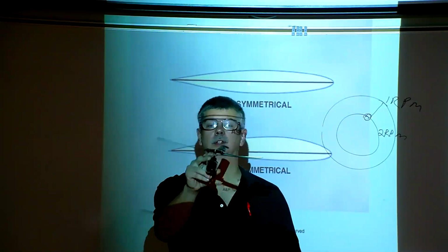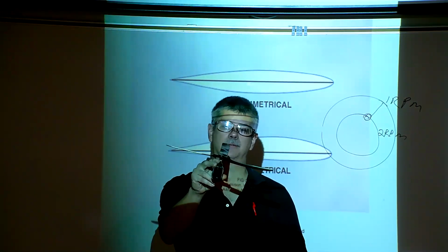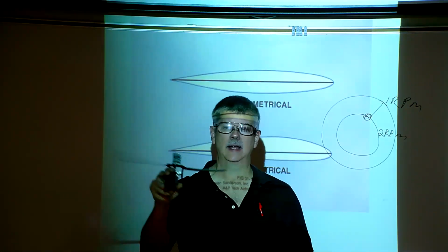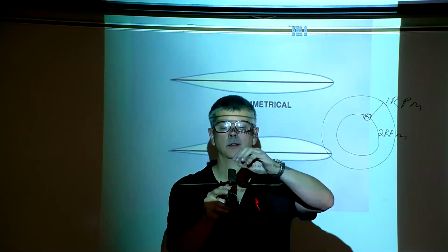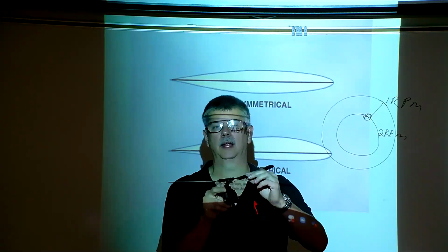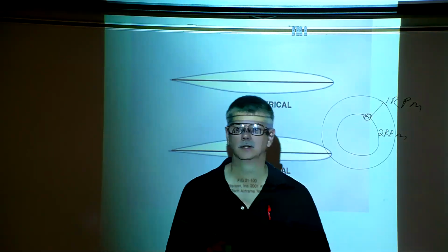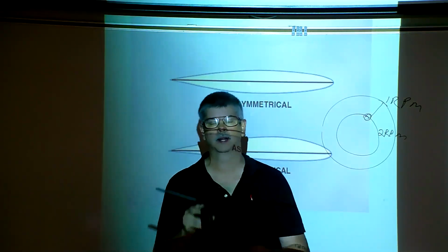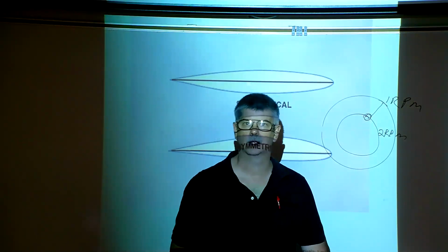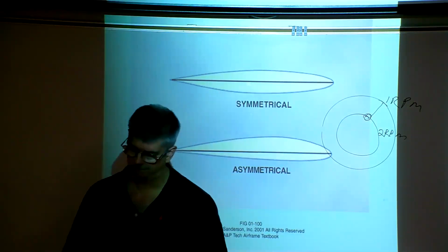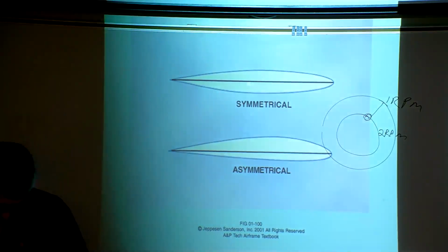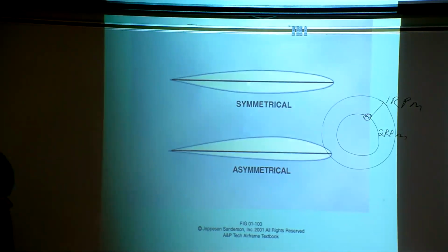One, they could tilt the rotor to the left so that it balances out that drift, or when rigging the rotor blades, the advancing blade has a slightly higher angle of attack than the retreating blade, and thus keeps the aircraft straight. And that was those two things.